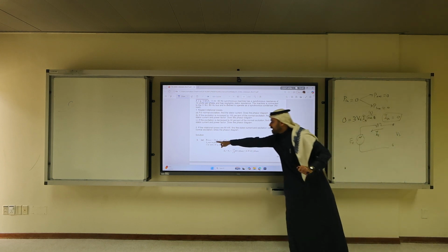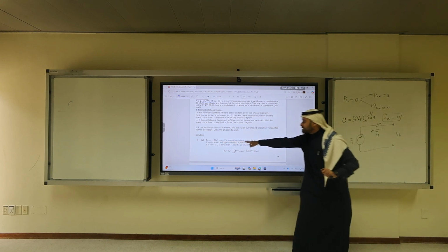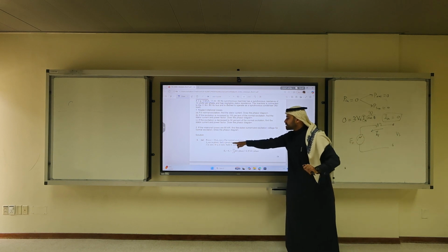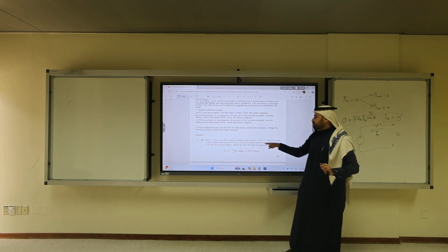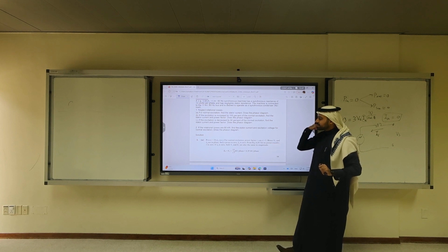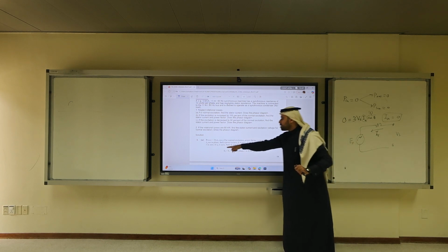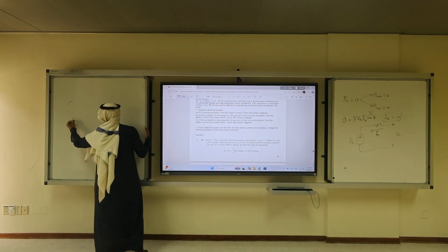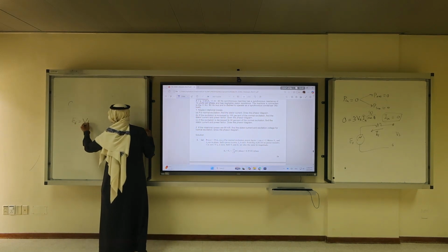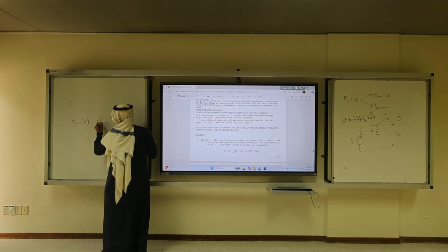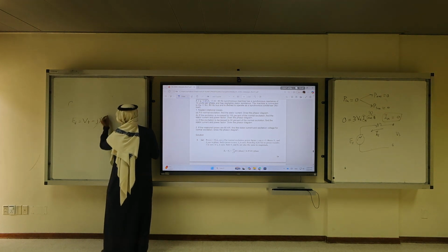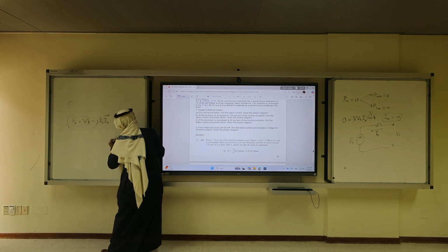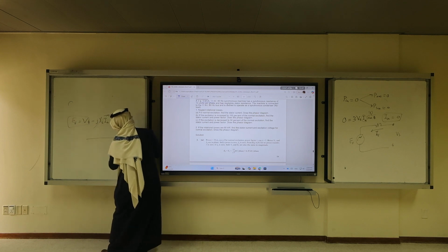If you read this statement, for normal excitation the power factor is 1, so VT and IA are in phase. Since IA is 0, from the equation there is no power transfer, so delta is 0. So this implies that EF equals VT minus jXS IA, and this is 0, right? So EF equals VT. How to do the phasor diagram? This is VT.